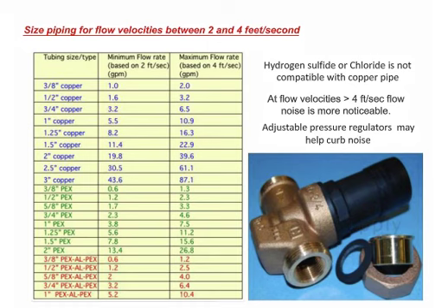But let's go down. Let's take a look at 3/4 inch PEX. Well, we're at 2.3 GPM and 4.6. Again, well below what you're probably going to need, but most guys don't understand that the internal diameter is smaller on PEX pipe, but remember guys, the connector goes inside the pipe. That's where your greatest restriction is. So again, I like PEX. I think it's a great material. You need to pay attention to the diameter and what you can get through it quietly.